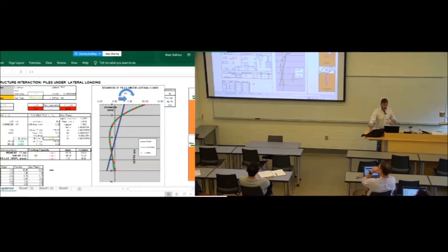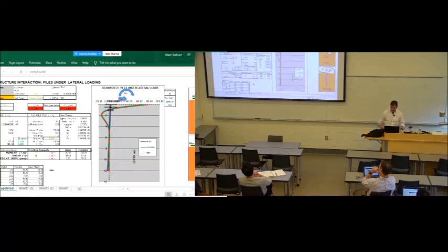If you take that 1.5 meter diameter pile, same soil, which is here, K, dense sand, and I put 0.5, it's more flexible. It flexes more. The deflection is 8 centimeters, so 80 millimeter. The riser means the distance of the pile above ground. Let's put 1 meter for now.